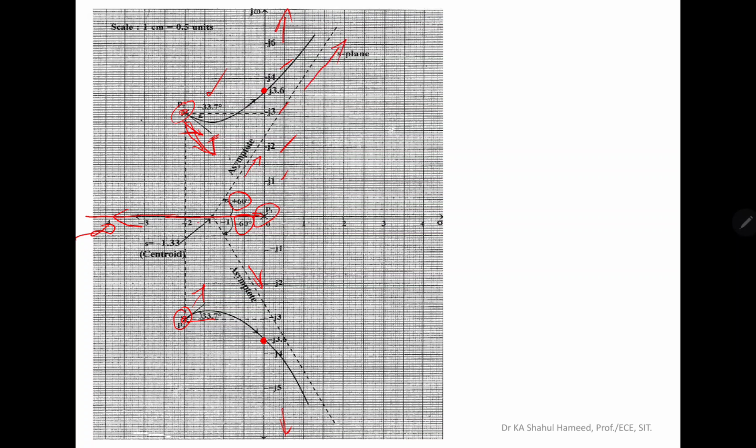So I am just starting the root locus branch, and I am slowly turning, and I am just touching the crossing point, and I am extending the line, and it will go parallel to the asymptote, and we have to assume that it meets zero at infinity.